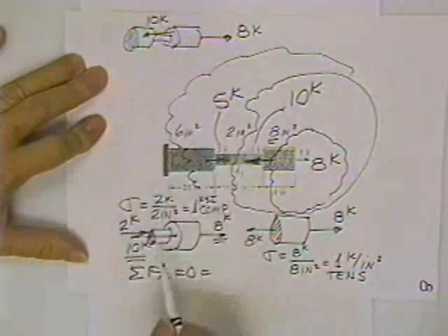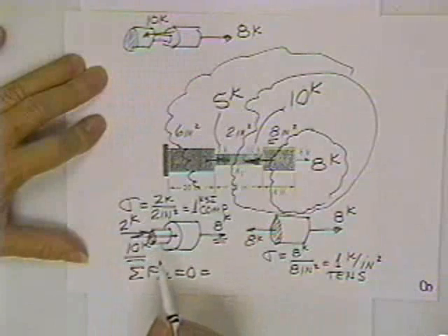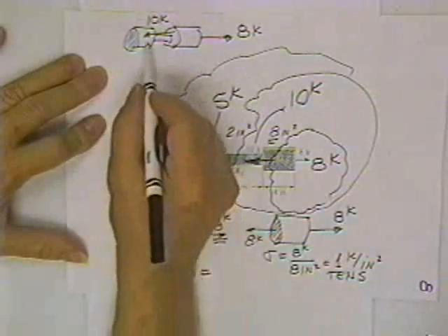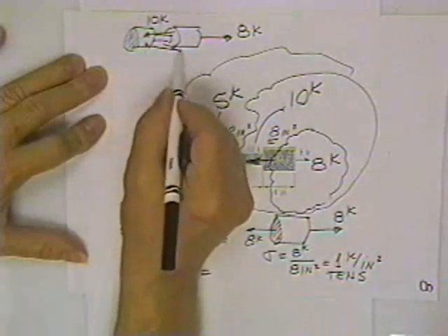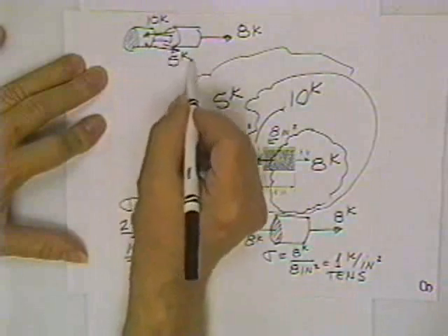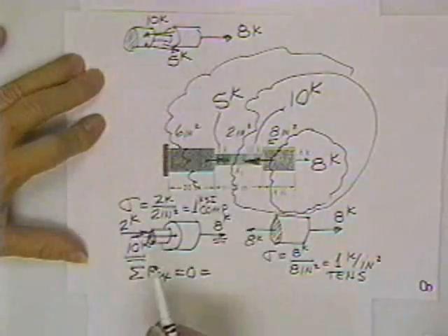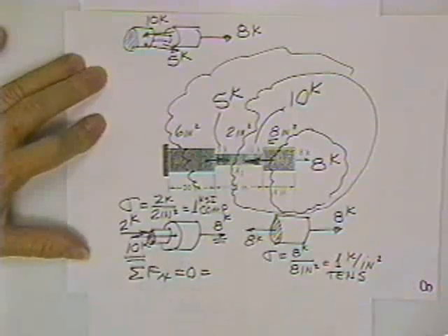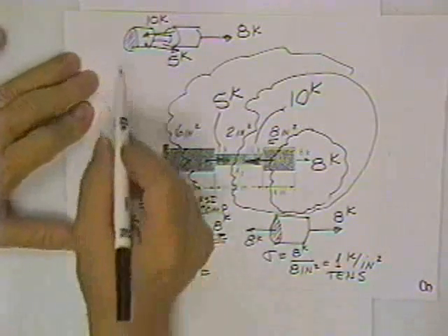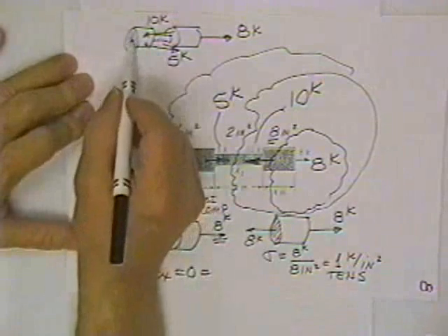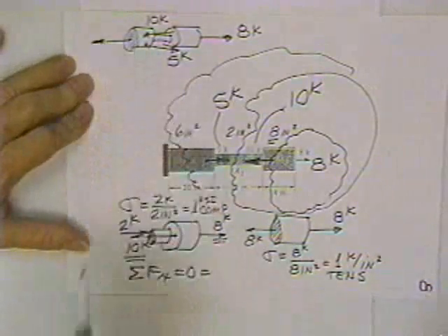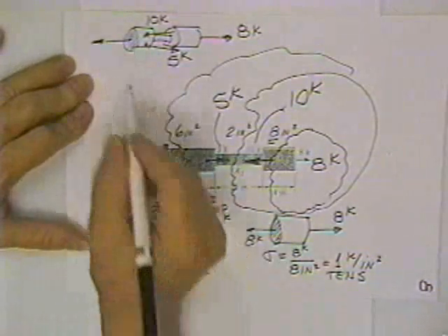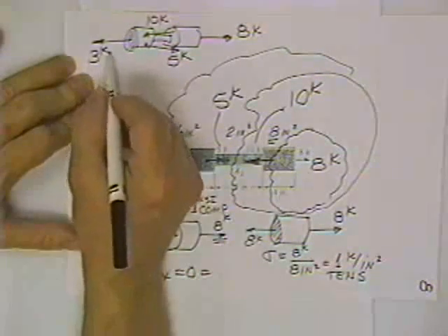10 kips to the left. There is a 5 kip load applied right here to the right. 5 kips. So all we've got to do is find out how out of balance it is. That's how much load will go in that new cross-hatched area. Was it 13 to the right? Beats up on 10 to the left. The 10 now needs some help. The force inside the piece of steel is 3 kips worth of load.